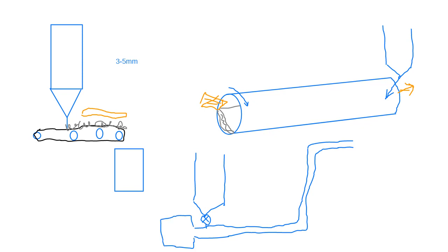Okay, so that's a pipe, a beautiful round and straight pipe. So we put in air over there, and we put in fuel over there, and that gets nice and hot. Let's call it 1,000 degrees C. So you've got gas moving along this pipe, and you've probably got some idea of how fast you can run gas in a pipe, and a rule of thumb would be about 20 meters per second. You've got wet particles falling into this pipe and being pneumatically carried along the pipe.